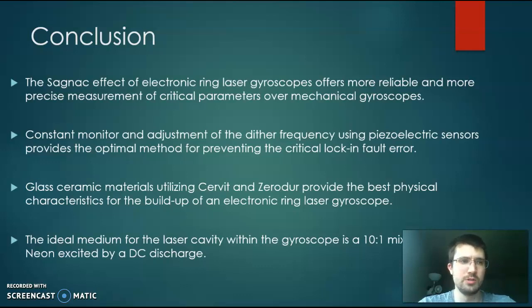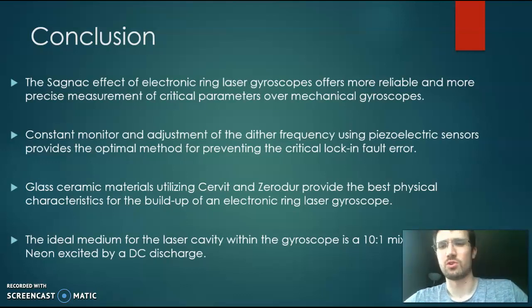In conclusion, regarding the hypotheses, the Sagnac effect of electronic gyroscopes is much more reliable than mechanical gyroscopes. Mechanical gyroscopes have largely been phased out of modern aircraft and replaced with these more advanced electronic ring laser gyroscopes.